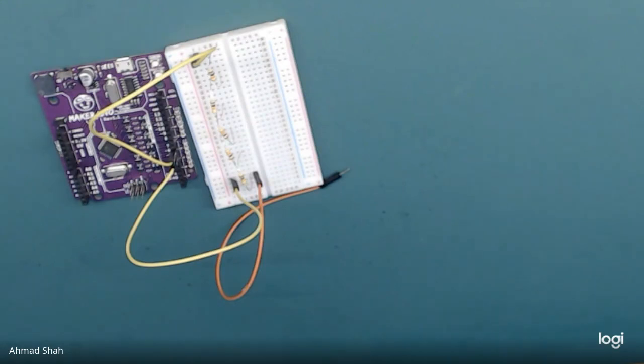After installing it, we will start the code, but we will check if everyone actually has the library first, because if you do not have the library, you are unable to run this code. One way to check whether your library is there is to type in the word capacitive sensor, like how Munir showed, include the library. Another way is you go to Sketch, then Include Library, then find Contributed Libraries and you will see capacitive touch.